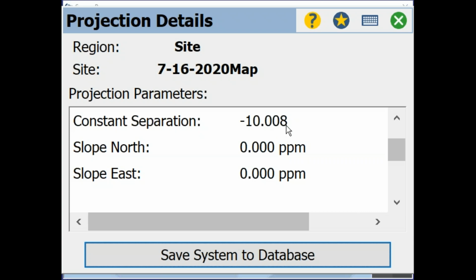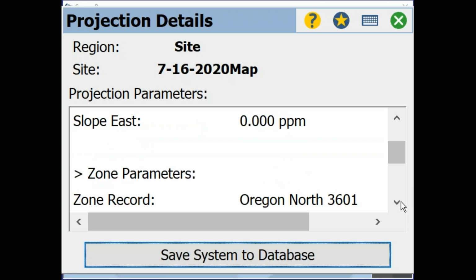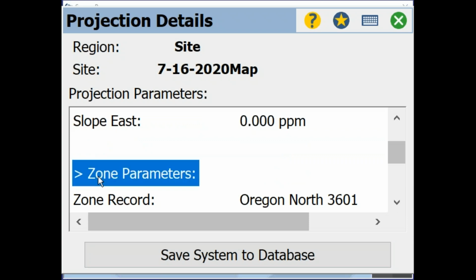And actually, the reason you're seeing almost a centimeter here is I prepared these control coordinates many years ago using Geoid 09, and we're applying a slightly different geoid here, so we get a slightly different answer. But to Joe's question, here's where you see the zone or the map projection that's being used underneath this calibration. Remember, calibration is just a similarity transform: shift, scale, and rotate one set of grid XY to another set of XY. One set is the control coordinates you provide, and the other set is the measurements through the GPS onto whatever mapping plane is in play.